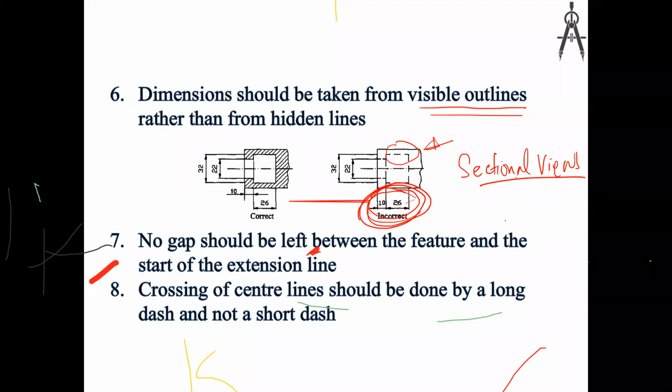For that purpose we make cuts. Like this in components also, if you want to see inside details, we cut it, but not really cutting, that is an imaginary cut. With our imagination we are cutting that component to see what is inside of it, or show what is inside of it. For that we use sectional views.